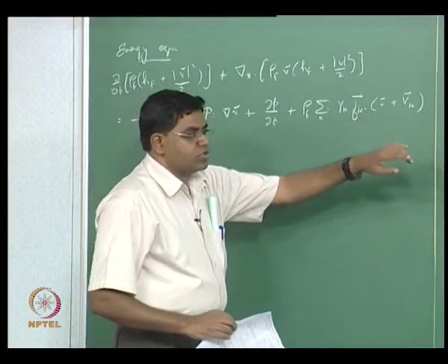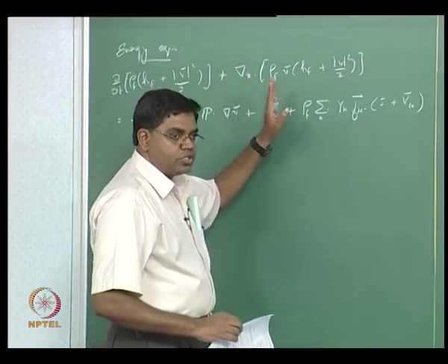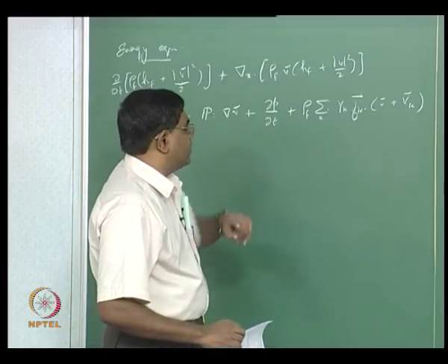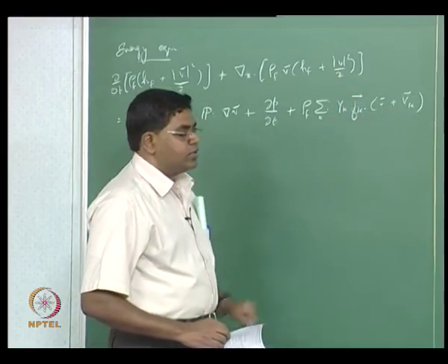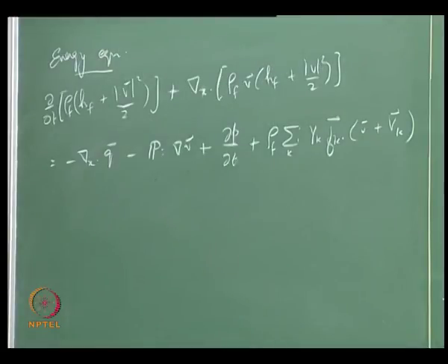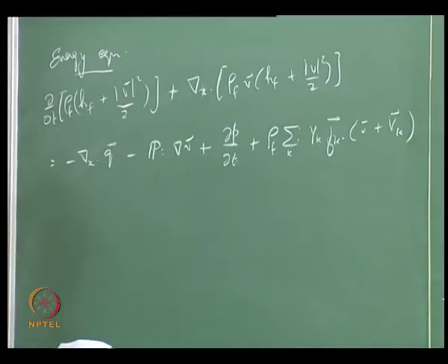Keep in mind this is what the momentum equation is all about. So this is the total energy equation. If you want the thermal energy equation alone, that would be by dotting the momentum equation with V, the gaseous mixture average velocity, so that this might go away, but this would still stay, right. The body force acts on the actual velocity of the species, which includes the diffusion velocity as well as the average velocity of the gaseous mixture. Minus, then you have a couple of terms specific to droplets.